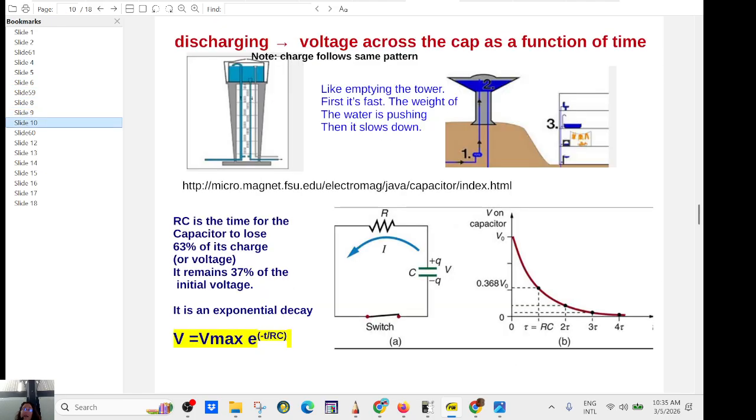So that will be the equation for the voltage across the capacitor. So a capacitor is resisting the building up of the voltage, right? You have a beautiful equation here. Everything is in the equation. And then I'm skipping the math, but then you have a discharge here. So that is called discharging the capacitor. At the beginning, it's going to be very quick because all the water here is pushing, wants to go down, and then it takes forever. This is called an exponential decay.